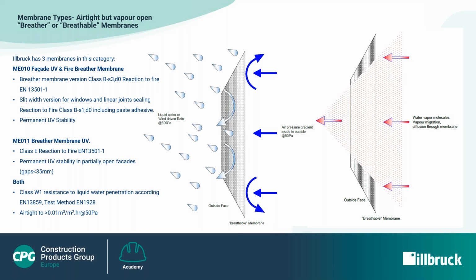A breathable membrane is a membrane that is available in a variety of slit widths and is also used as an external seal as applied to window, door and curtain wall perimeter joints. A breathable membrane and a breather membrane should resist liquid water penetration but allow moisture to diffuse through it. Diffusion is required because of the changes in relative humidity and resultant saturation pressure on the cold side of the wall, where dew points are lowered and are highly exaggerated beyond the heated, conditioned environment of the occupied spaces.